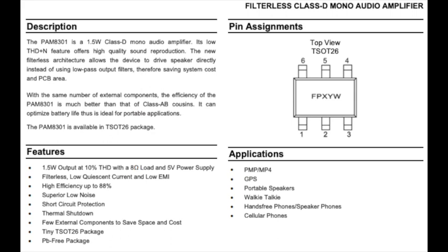One of the big benefits of using it is that it requires a very low component count to implement. At minimum, you need a capacitor for your signal in, a decoupling cap on your power input, and maybe a pull-up on your shutdown pin. In the datasheet on page 8, under application information, it talks about how to reduce EMI, and it does suggest using ferrite beads and some filter caps there, but only if you're using external speakers.